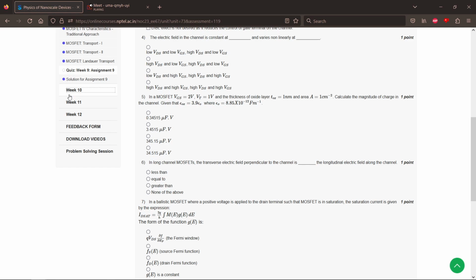Just out of curiosity, correct me if I'm wrong: are FinFET devices single gate devices or multi-gate devices? FinFET devices are typically multi-gate devices, because I essentially grow the gate as a fin. The planar structure has been discarded and now it is a 3D model. Since we are doing a fin type growth over there, it is a multi-gate device.